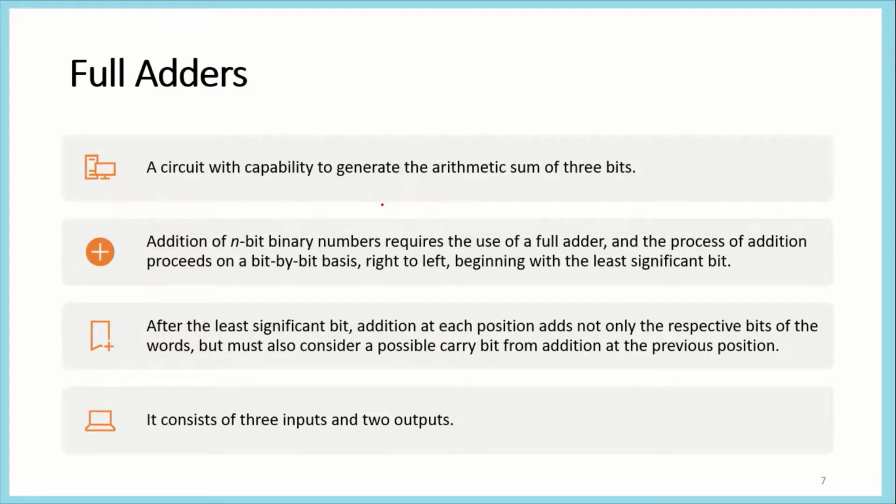So considering that extra bit, we need an extra input in our system, generally represented as C in, carry in, or Z, or by any other variable. So a full adder is an extension of half adders, where we are now dealing with 3 inputs instead of 2.